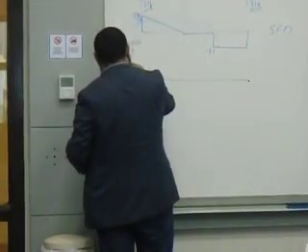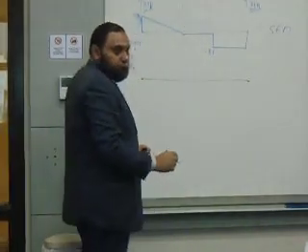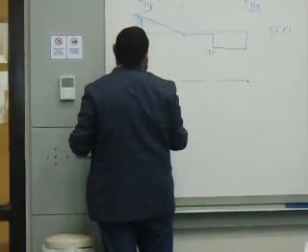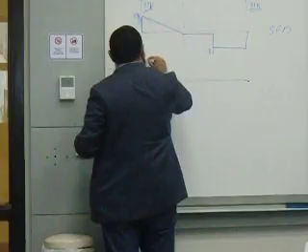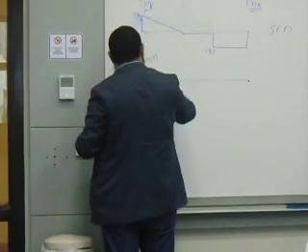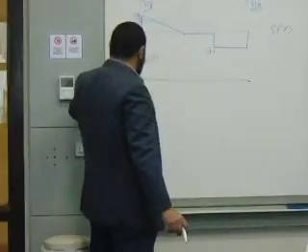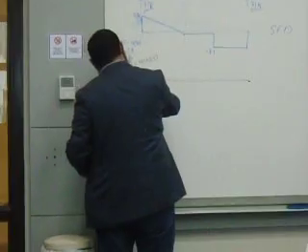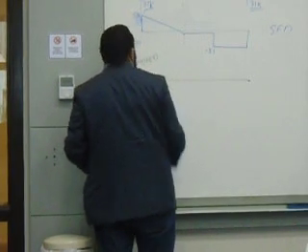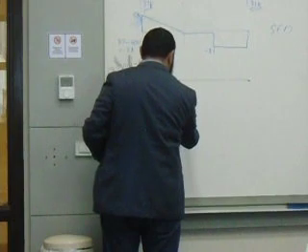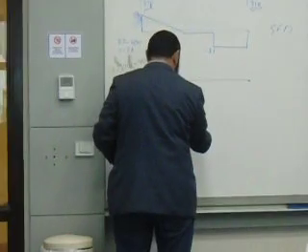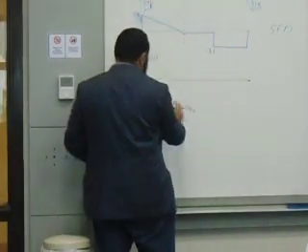37 times 10. This is happy, it's positive. Minus 4 times 10 times 5. So this is 370 and this is 200. So this is 170 kip-feet. So I'll simply say, I'm in the positive, we plot it below in the bending moment diagram. So this is 170 kip-feet. Focus with me.